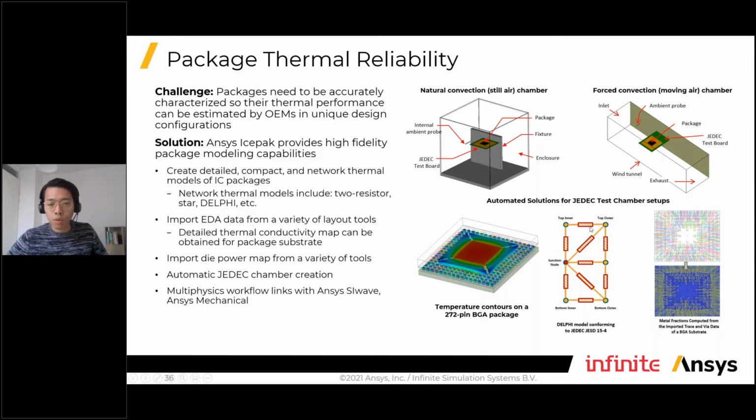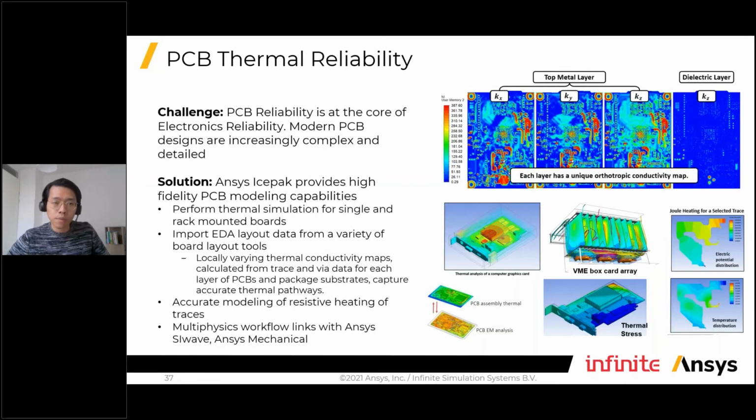So what we can do is simply extract a thermal circuit, as you can see here. Using the thermal circuit, we can describe the chip performance as a single object, and then quickly learn how it will interact with the environment.